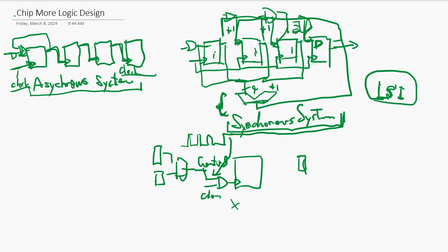So if the clock is high, during the high, all those control pulses are transitional logic states that cause wrong clocks into this flip-flop. So you never do this. This is a very bad design.